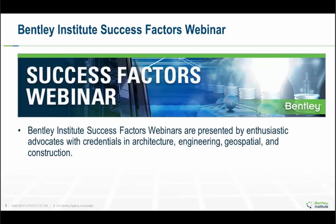Fortunately, the software that we use today, whether it be RAM Structural System or STAAD or something else, offers the ability to do P delta analyses. And I would take some time and experiment, see, well, what happens if I do this? What happens if I do that? When does this become a problem? When do I start seeing it? And I really find the B1 and B2 factors very useful for that, because I can run an analysis and then look at those numbers and get a very good idea of what it did to this member, or this story, or this building.